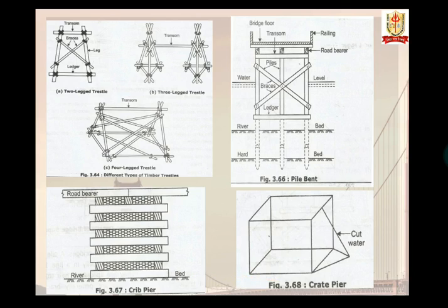Timber trestles. These are usually constructed for valleys, round or square in section, or formed from tree trunks when a heavy section is required. Trestles with round sections are fixed together by ropes or steel wires at their joints, but in the case of the square section, spikes and nails are used for these purposes.